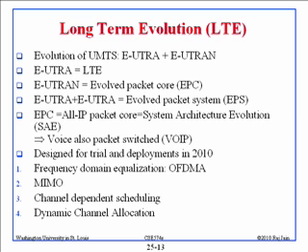Alright? So that was not there before, and so we had tough time doing equalization, and because of that we could not use big bandwidth. Like maximum that they could use in CDMA was 5 megahertz. With 5 megahertz you cannot go to 100 megabits. Right? So if you want to go to any high speed data, you really need to do this wide channels, and for that you need OFDMA, so everybody is going to OFDMA.